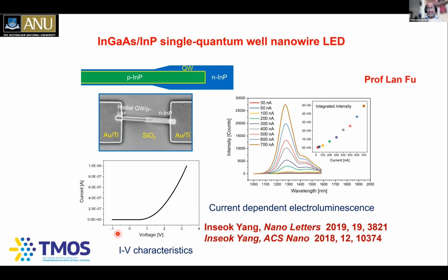So you can see the IV characteristics showing a nice, beautiful diode-like structure, showing that In-Soo's hard work paid off. He's able to demonstrate nice PN junctions, and also to make nice ohmic contacts as well. Then he looks at the light emission as a function of injected current.